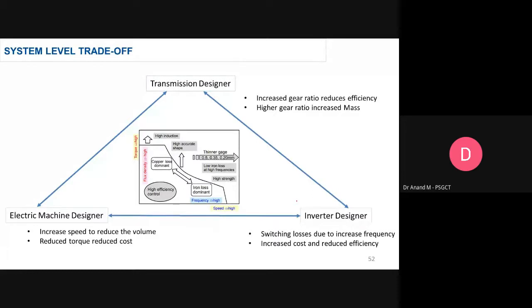At last, to summarize, the system trade-off of an electromagnetic drive system is a trade-off between 3 design teams: the electromagnetic team, the traction inverter team, and the mechanical transmission gear design team. Because we could see that if I concentrate on the constant torque region, the copper loss may be dominant. If I concentrate on the constant power region, maybe I have to sacrifice the iron loss. So it's all a trade-off between the maximum yielded flux density, the power density that you can stack within the defined volumetric constraint D&L, and the frequency at which we are going to design the entire powertrain.